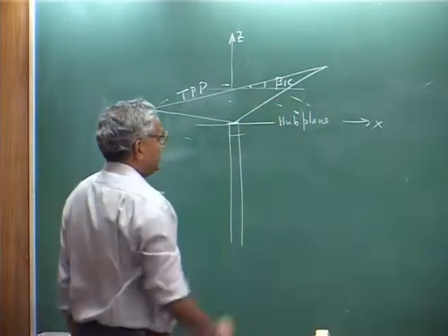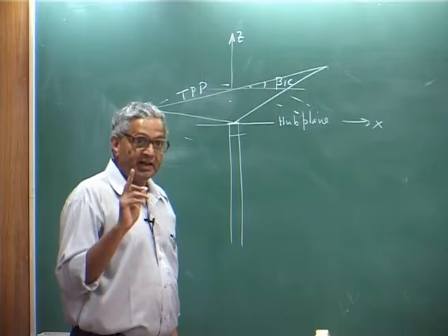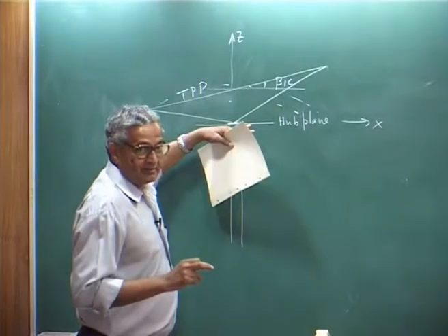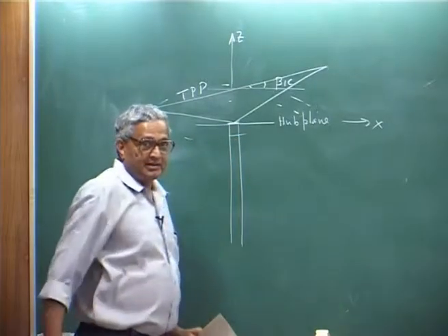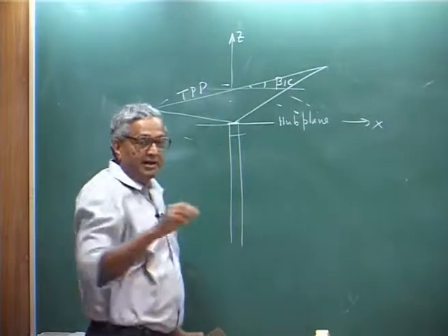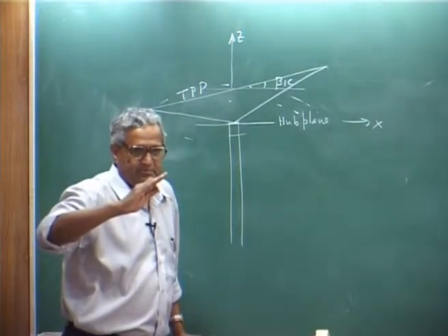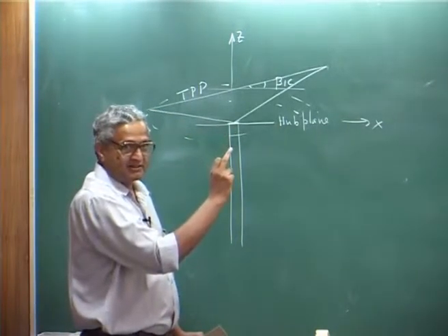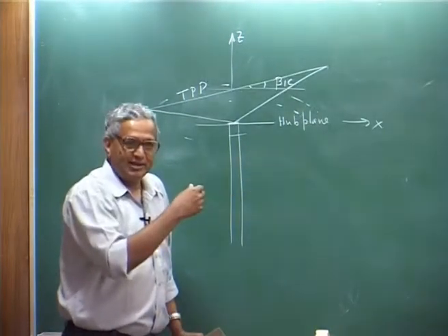I am looking at it this way, in this y direction. The pitch angle I give when the blade is at 90 degree, I give a theta 1s which is positive. You assume that you are giving a positive pitch angle, and then when it comes to 270 you give minus, because sin 270 is negative.